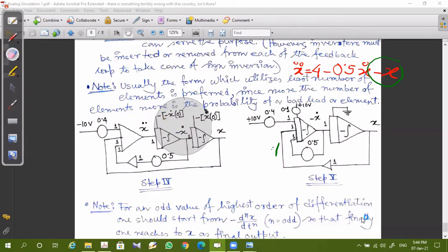Now, this is not all. See, in this connection, there are 1, 2, 3, 4 in fact. See, this 1, 2, 3, this connection is redundant. Why? Already you have seen that this integrator has 5 input ports, right? So we are using only 1. Rather, we are using a summer, an inverting summer. So this will complicate the situation. There will be more connections, more possibilities of loose contact, a more complicated circuit, more wires involved.